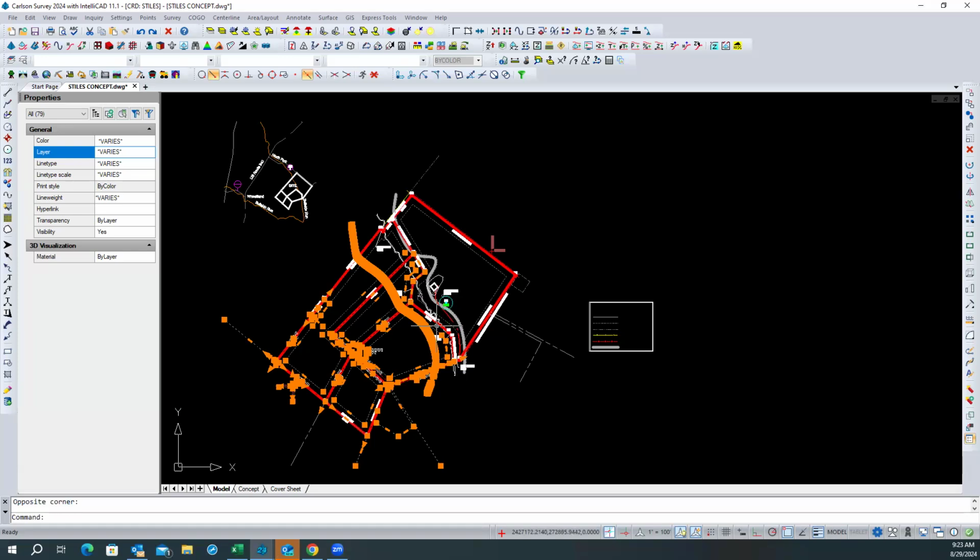You see the little segmented part? You're not getting the window to activate. What am I doing wrong? Press escape on that. Now hold the shift key, click in the blank spot and drag toward the left to where you cross that stuff that's lit up. There you go. That should do it.